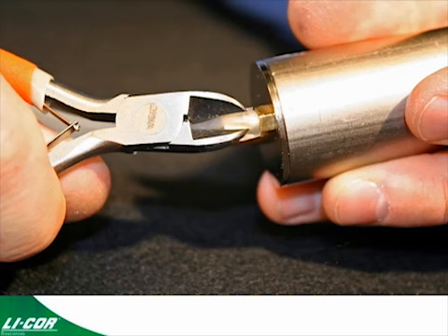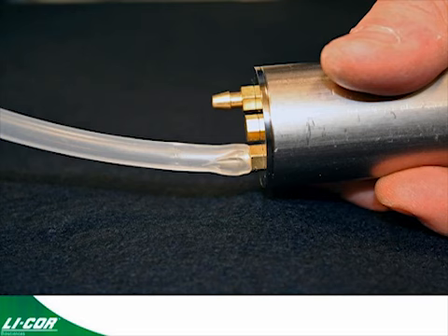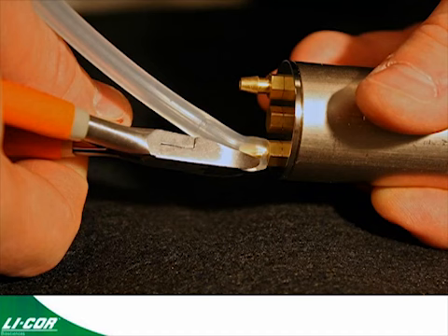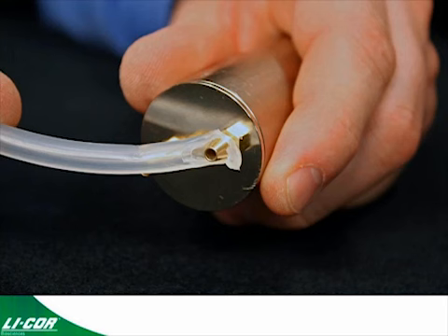Squeeze the tubing, do not cut all the way through to the hose barb, and then gently pull that tubing away, stretching it on the hose barb. This allows you to move the tubing away from the hose barb without cutting all the way through. Once you get that tubing stretched away from the hose barb, then go ahead and cut all the way through the tubing. This will leave a small fringe around the hose barb that can easily be torn off.